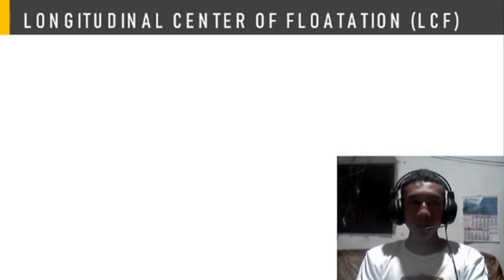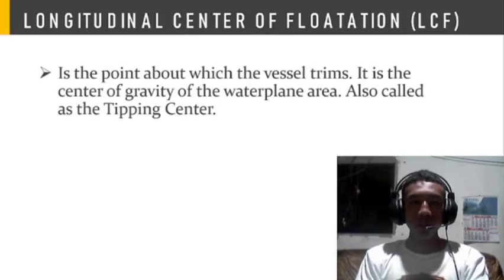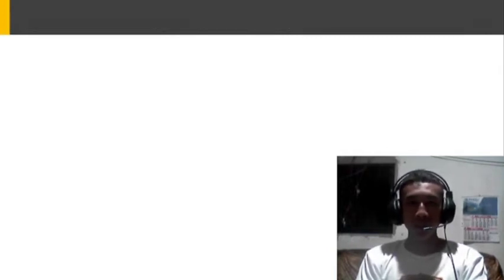Next, the longitudinal center of flotation, or LCF, is the point about which the vessel trims. It is the center of gravity of the waterplane area, also called the tipping center. So it is the geometric center of the ship's waterplane. So this is the LCF, or the longitudinal center of flotation.